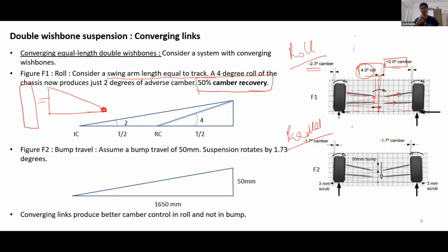So ideally, we know how much camber, during cornering, I would like, if not a negative camber in my outer wheel, I would at least like the outer wheel to be perpendicular. And during straight line motion, I would like to have zero camber for my wheels, right? So that is the objective now.